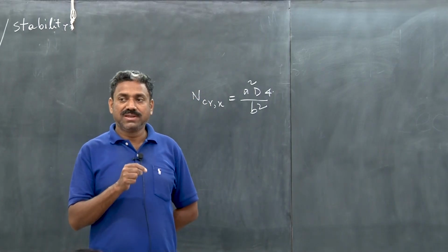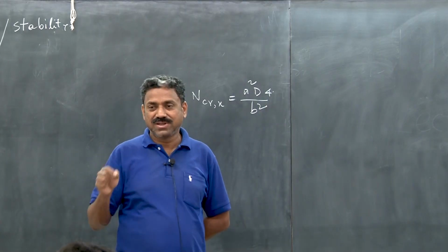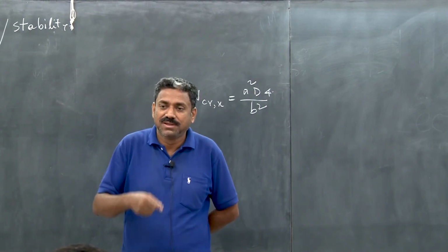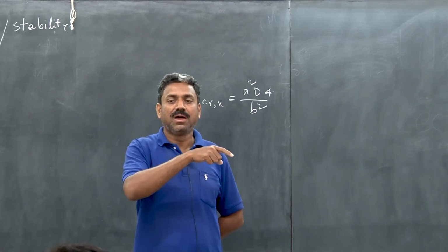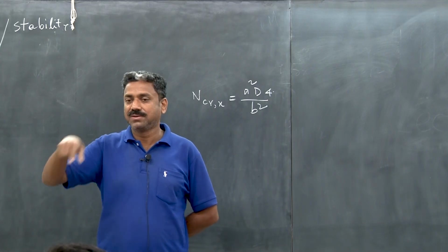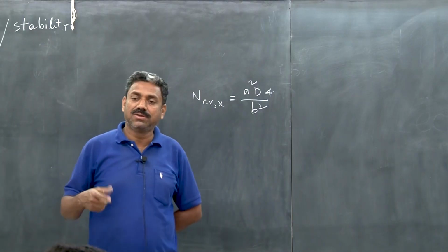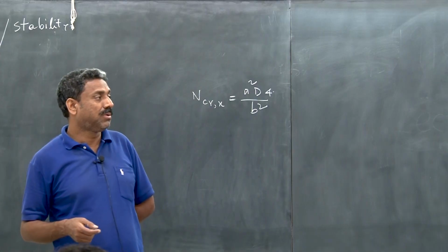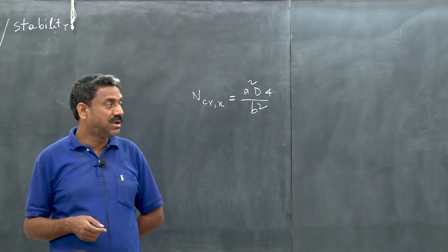And with increasing aspect ratio, mode shifting occurs from the first mode to the second mode to the third mode. If you see the curve with changing aspect ratio, the increase in the critical load follows a boundary like a tongue kind of structure, which is referred to as Arnold tongue, and which is a very general kind of structure that you observe not only in buckling of plate, but in many other scenarios, especially in dynamical systems and other non-linear dynamics.